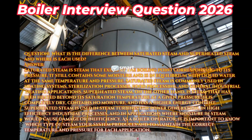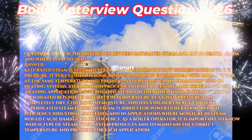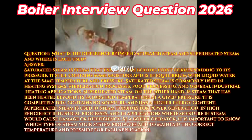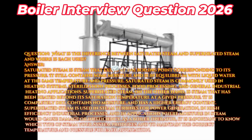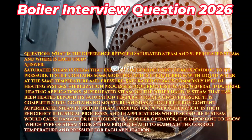Superheated steam, on the other hand, is steam that has been heated beyond its saturation temperature at a given pressure. It is completely dry, contains no moisture, and has a higher energy content. Superheated steam is used in steam turbines for power generation, in high-efficiency industrial processes, and in applications where moisture in steam would cause damage or inefficiency. As a boiler operator, it is important to know which type of steam your system produces, and to maintain the correct temperature and pressure for each application.